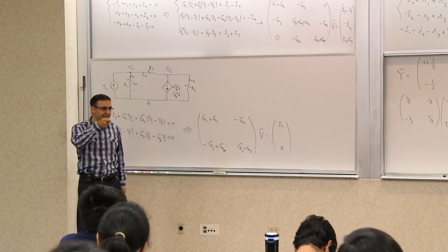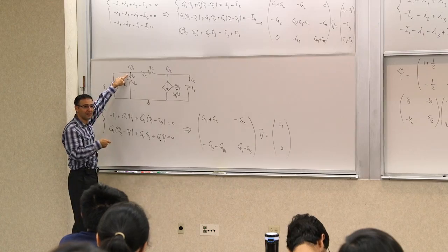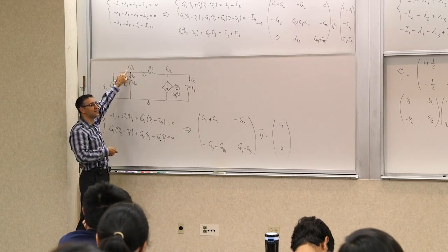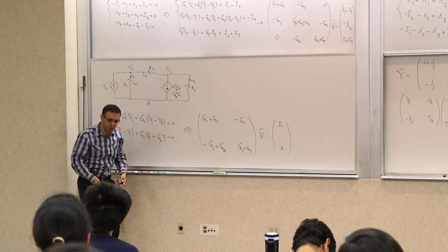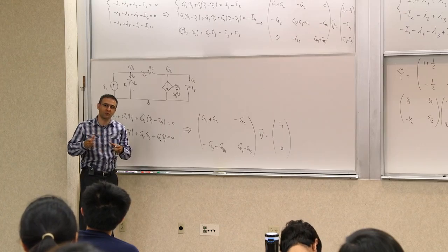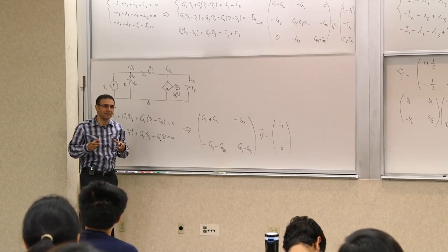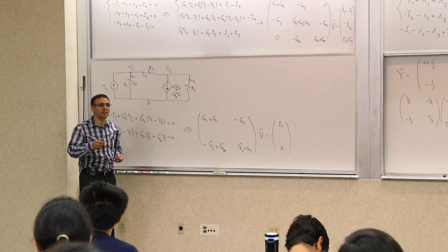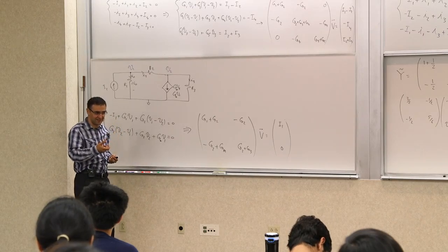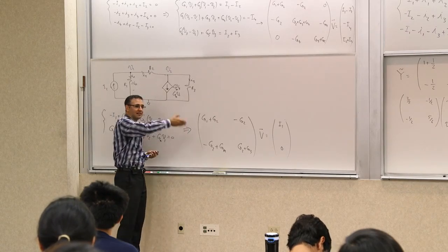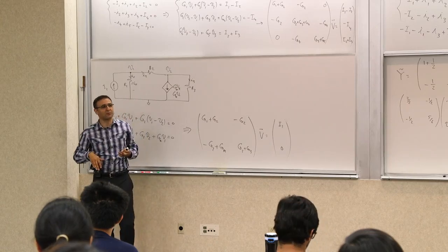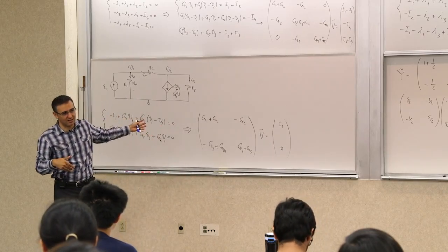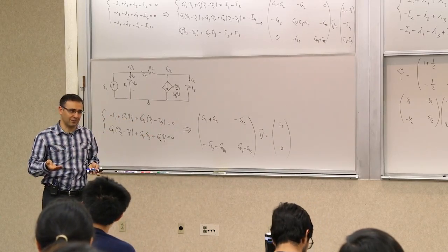So that's the gate. That's this terminal, controlling it. If I increase the voltage on that terminal, I get more charge carriers inside the channel, which means my resistance is going down. So I produce a smaller resistance, so that can carry more current. So that's one way to approximate this, for example. Again, there's a lot more to it.